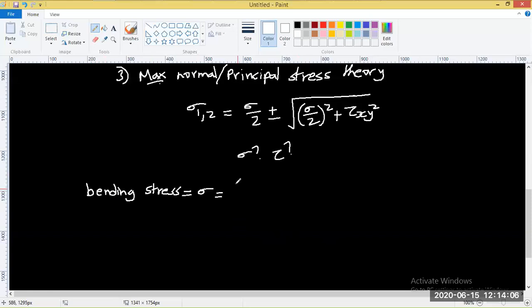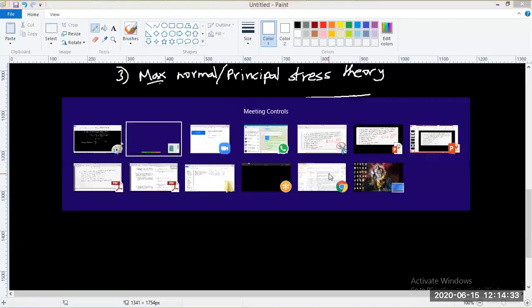So that is bending moment MB by I, moment of inertia, into C. Okay, so this equation also I think you are familiar with. You have used it multiple times so far, where I is the moment of inertia for circular cross section. For circular cross section, you need to refer to the data handbook, as I told you before. I'll show you the data handbook.